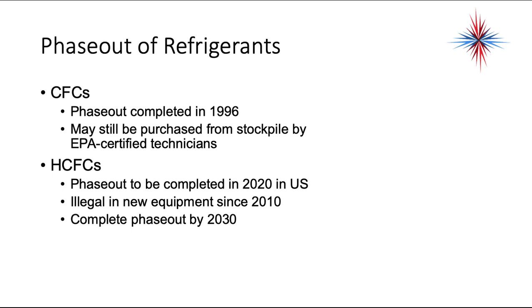We have some phase out of refrigerants we have to think about. CFCs, phase out completed in 1996. It can still be purchased from a stockpile by EPA certified technicians, but there is not much left, and it's very expensive.